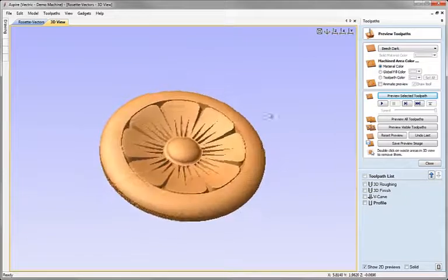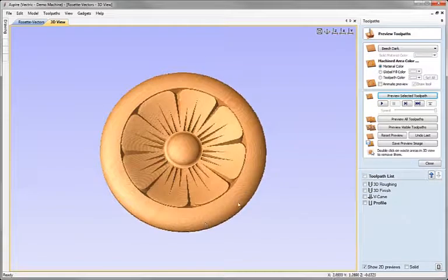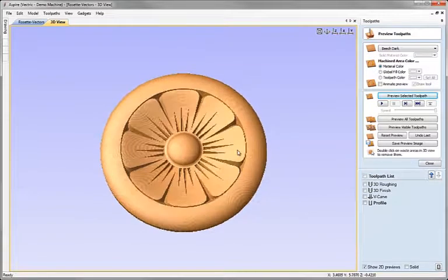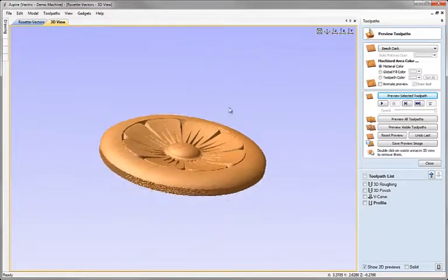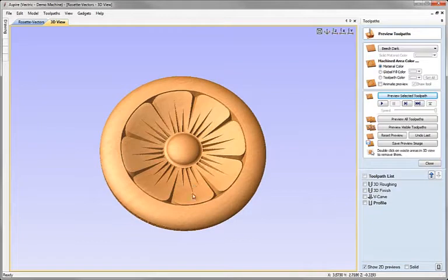and then we can double click on the material on the outside, maximize the 3D view, and now we can actually see our 3D part and how that toolpath that we chose, the V-carving, once projected onto the 3D model, created the decoration exactly as we wanted it to in relation to the 3D shape that was underneath it.